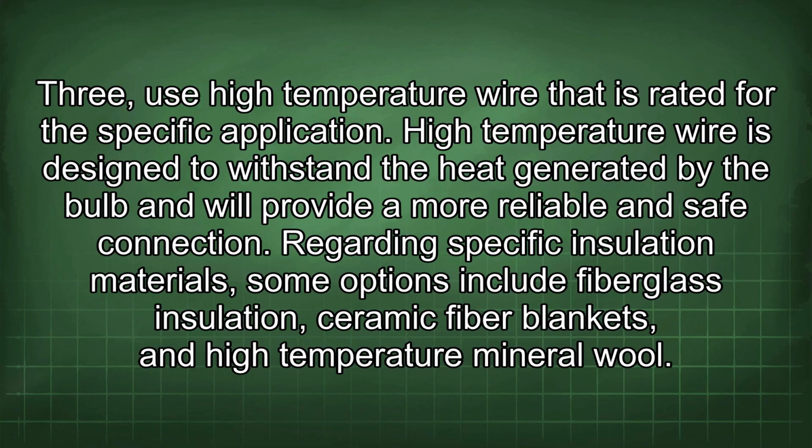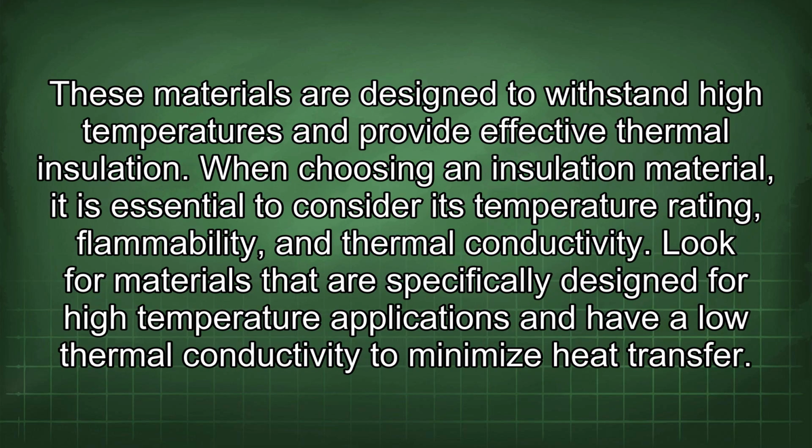Regarding specific insulation materials, some options include fiberglass insulation, ceramic fiber blankets, and high temperature mineral wool. These materials are designed to withstand high temperatures and provide effective thermal insulation. When choosing an insulation material, it is essential to consider its temperature rating, flammability, and thermal conductivity. Look for materials that are specifically designed for high temperature applications and have a low thermal conductivity to minimize heat transfer.